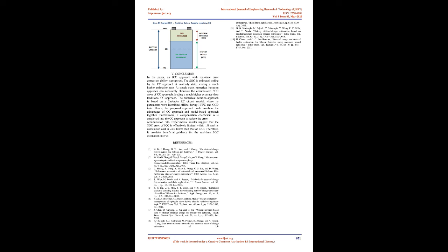The battery operation mode can be known from the amount and the direction of the operating current. The DOD is adding up the drained charge in the discharging mode and counting down with the accumulated charge into the battery for the charging mode. After a correction with the charging and discharging efficiency, a more accurate estimation can be achieved. The SOC can be then estimated by subtracting the DOD quantity from the SOH. When the battery is open-circuited with zero current, the SOC is directly obtained from the relationship between the OCV and SOC. It is noted that the SOH can be re-evaluated when the battery is either exhausted or fully charged, and the battery operating current and voltage are specified by manufacturers.